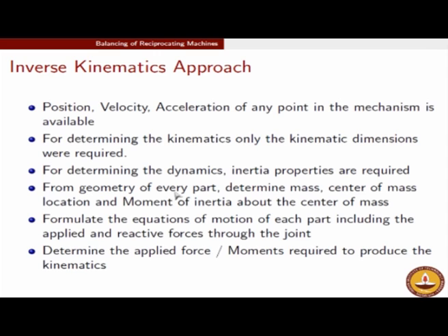In the forward dynamic approach, as you would have learnt in your engineering mechanics class, you would have been given the forces, and given the forces you try to find acceleration. From the acceleration you integrate to find the velocities, and from the velocities you integrate once more to find the position. But in the inverse approach, you first fix the kinematics and then determine the forces which will cause this kinematics. So this is the inverse approach which will be taught through this lecture.